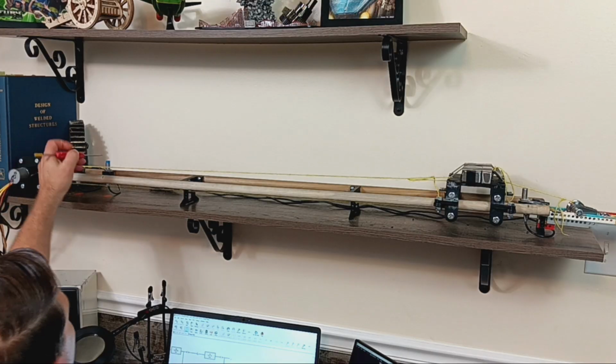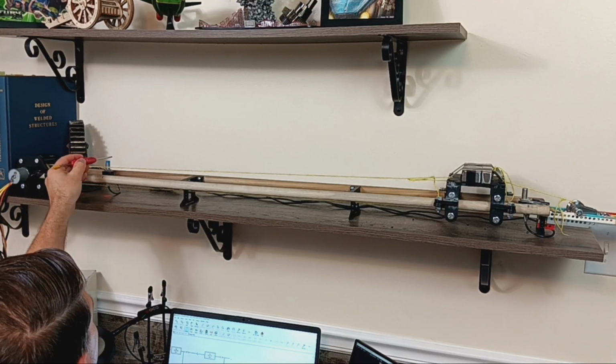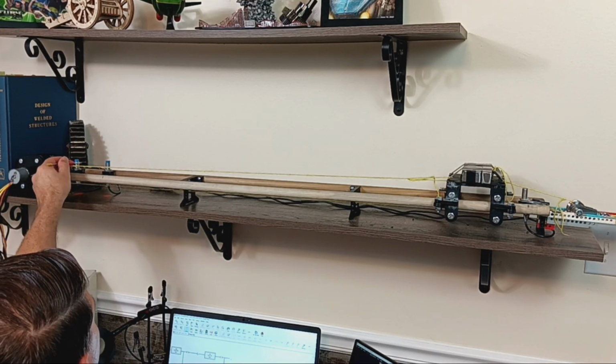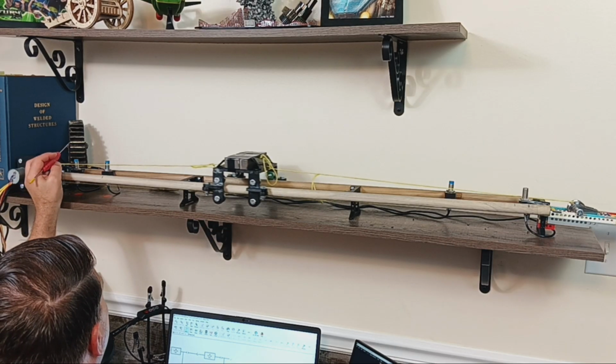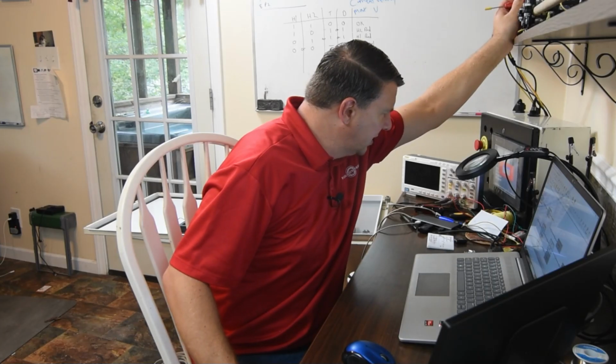Now, another error here that I want to show you is this one that says high 1 prox not found. And that will occur if I am homing for the maximum and I don't hit this one, but I hit the second one. All right, it says I should have gotten a prox there, but I haven't. So why is that? And let's fix that. So here I'm going to launch it. And after it launches, I'm going to quickly hit this one. All right. So it says high proximity switch not found. Gives me an error there.